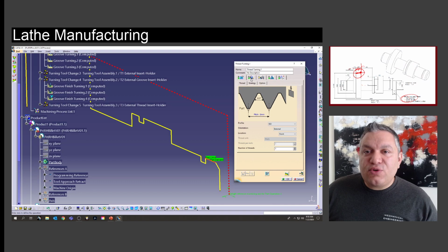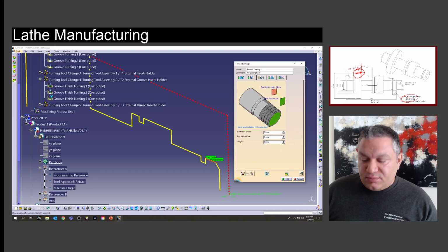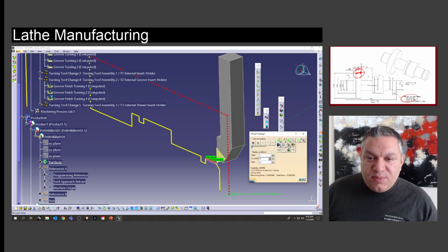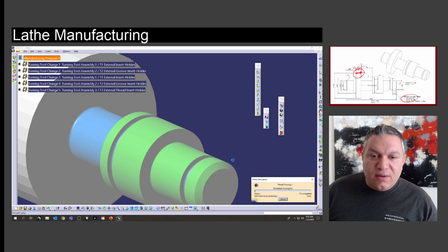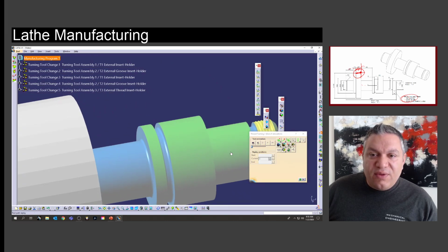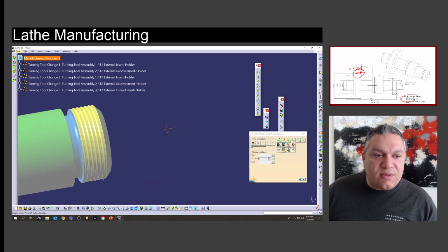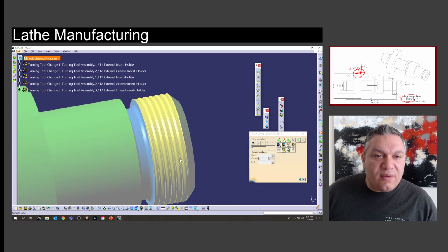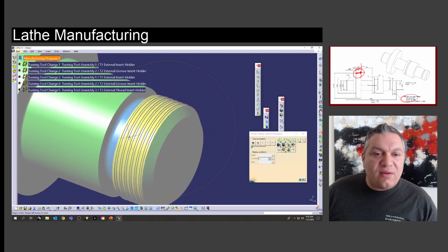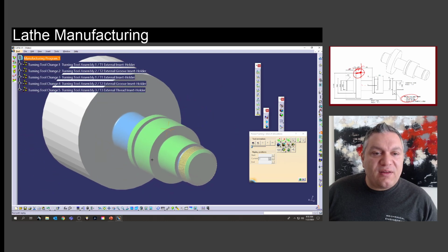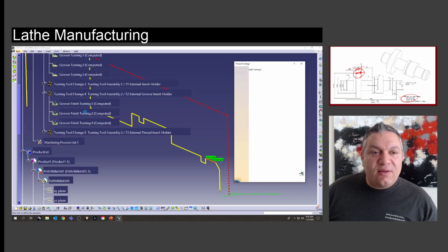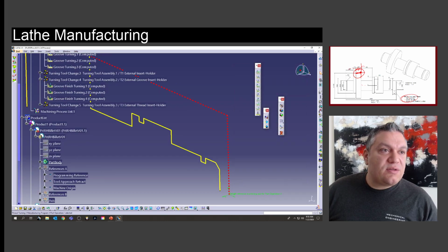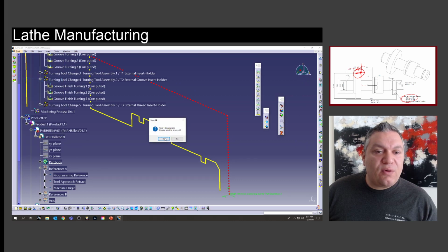Let's make sure that we put the length at 11 millimeters. Let's see this one. Well, it looks perfect. So we go here, we created, and we have our thread. This is a beautiful thread that we have, according to the pitch that was provided. We have the part, we save, and we are done with our first, so save all.